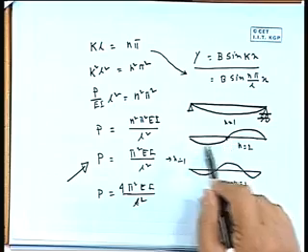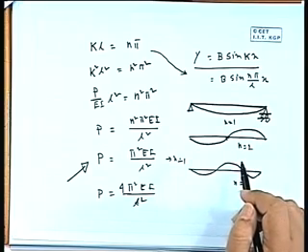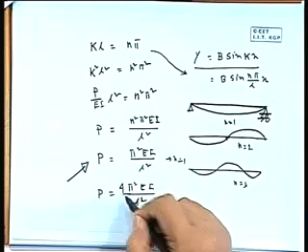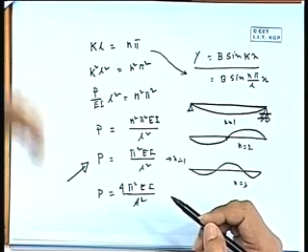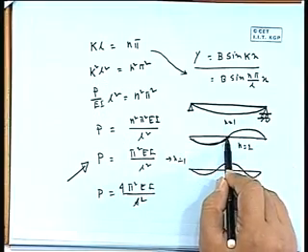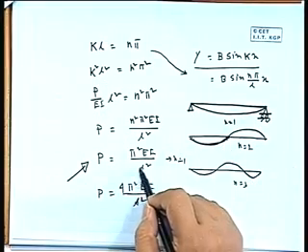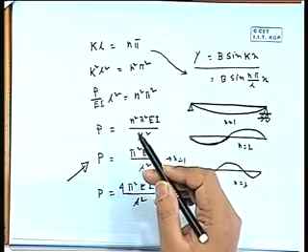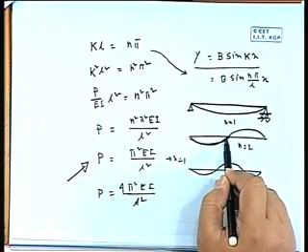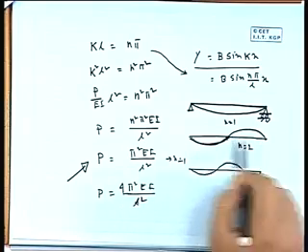So there might be a little gap, it is not fully ensured, but anyway due to some physical constraint it can't undergo movement. So what will be happening? It will start to buckle in the second mode, because here it can't, so automatically it will take that shape. In that case we will get 4 times the buckling load. So it is n square, so if n is 2, it will be 4, so the buckling load will be increased. We can say this part is represented like this, so this will be L by 2, so if I do L by 2 square, automatically 4 will go there. So you can think in that manner, it is a hinge here, or it is the second mode, and this is a support.